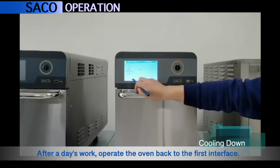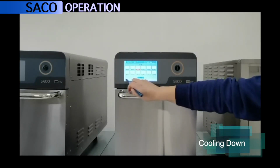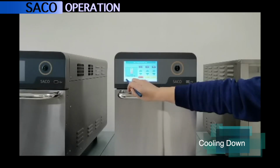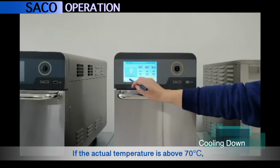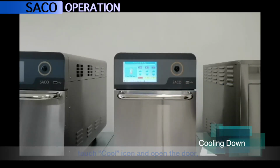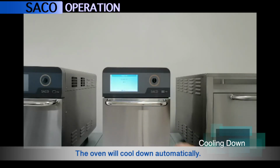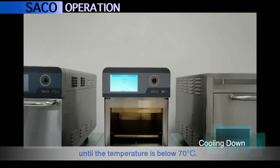After a day's work, operate the oven back to the first interface. If the actual temperature is above 70 degrees Celsius, touch Cool icon and open the door. The oven will cool down automatically. The cooling down interface appears and stays on until the temperature is below 70 degrees Celsius.